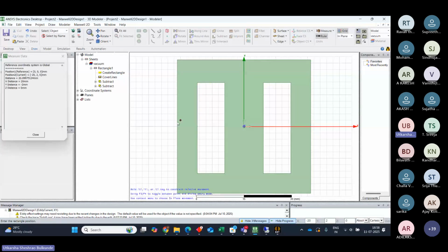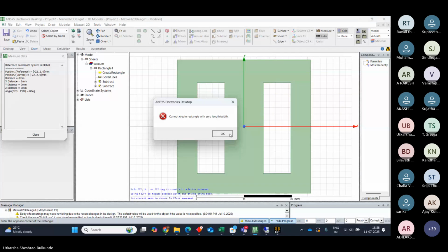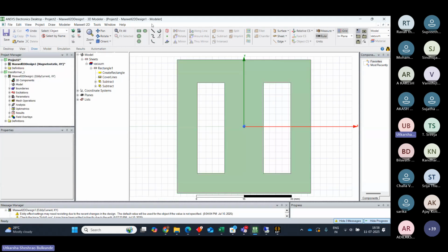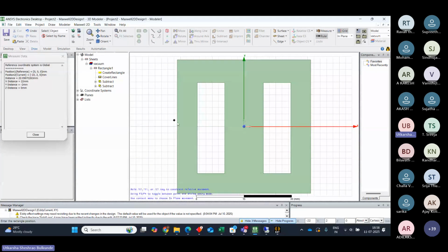Now we will introduce some air gap in the core. So it's of 0.2 mm air gap. I'm rushing here because you already know how to draw this geometry. Do you guys want me to repeat this again or it's fine? No, ma'am. Right. Okay. So now we will introduce 0.2 air gap here. Let's draw one rectangle first, then we can just adjust it later.